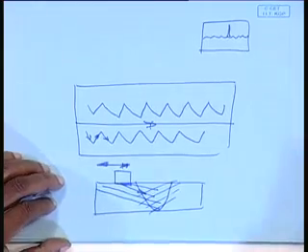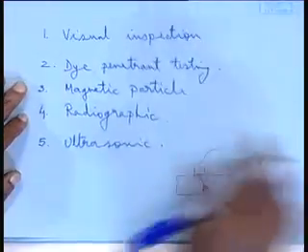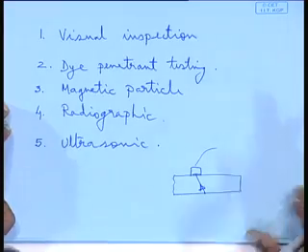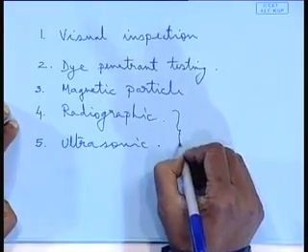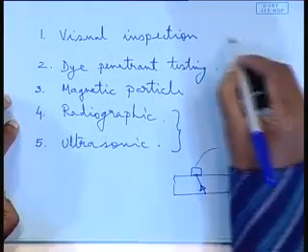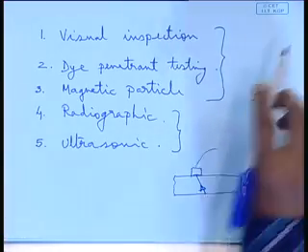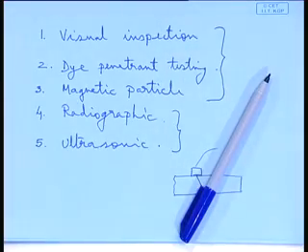That is another biggest advantage of radiographic and ultrasonic testing, that you can produce a record of the tests. That is very, very important from a legal point of view, because you know what happens, all these assume immense importance if an accident takes place. In the service life, if some accident takes place, then you start digging out, start a post-mortem and all that.